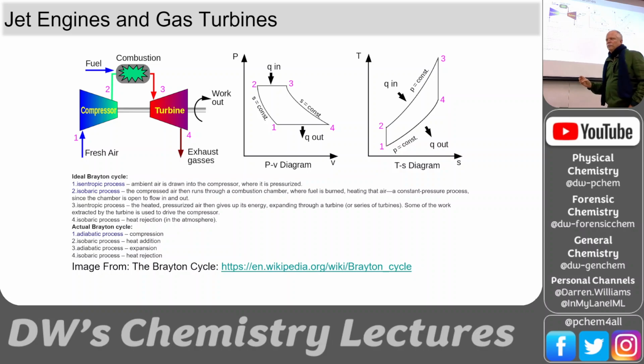Now, on our military jets, we have what's called afterburners. And so then they put more fuel out here in the back with the exhaust, and it's more like a rocket than a turbine. They're just spraying fuel out and creating thrust by putting fuel after the turbine. So it's not very efficient because they're just burning through tons of fuel, but it does give you an incredible boost.